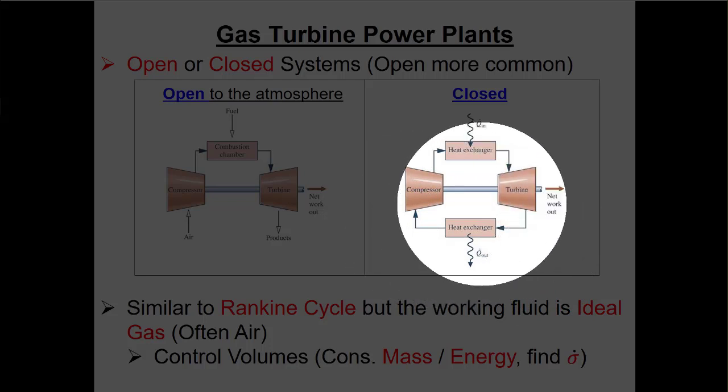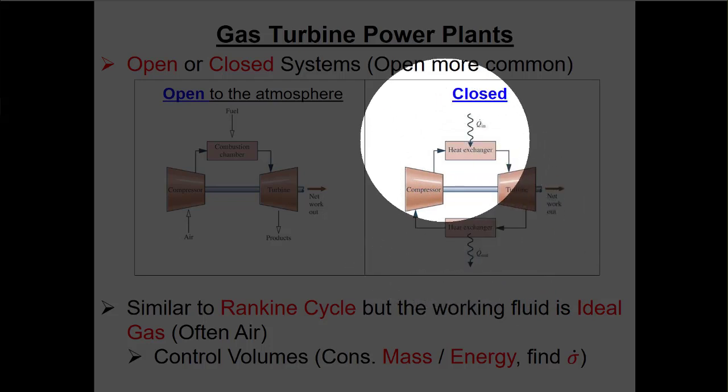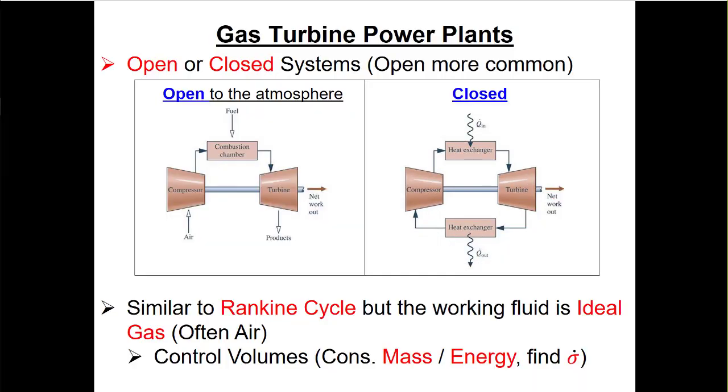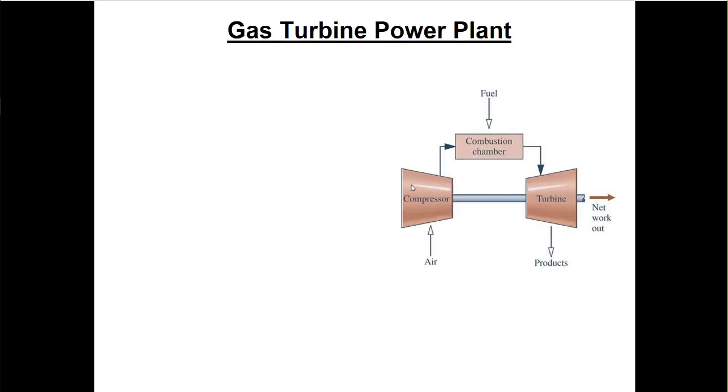And then we cool it off, right? Because Kelvin and Planck told us for every heat engine, we need a heat sink. So we cool it off here, then we compress it, then we add some more heat, and we just keep going around and around and around, right? So it's like a Rankine cycle because we'll use the open versions of the first law and the second law, but it's like an internal combustion engine because when we ask ourselves, what's the fluid? Well, the fluid is air, right? So the air is an ideal gas, so we'll use the same strategies as we did in the internal combustion engine, which means that we have to look for those isentropic processes. So, keep in the back of your head, we're going to be looking for ideal compressors and turbines to use either an expression that's got a VR or a PR in it or a k in the exponent.